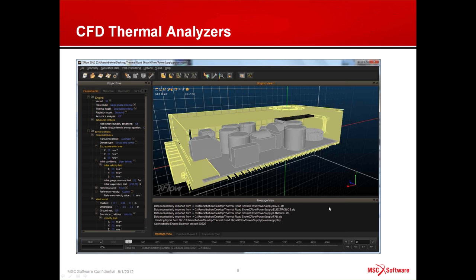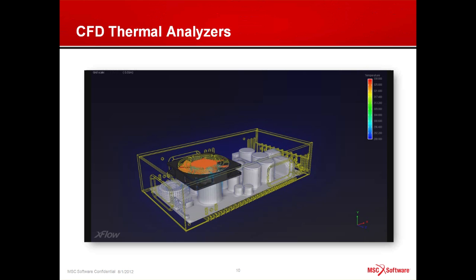Now, to model convection, some people use something like XFlow, which MSE can provide. And here's a model of an electronic box, and CFD codes are sometimes used for electronic packaging, but they tend to be very slow and take hours or many hours to run. This should start flowing a little animation here. And you can see you get a lot of detail on the airflow, and you get a great understanding of the airflow, but they're usually pretty weak when it comes to the thermal side.